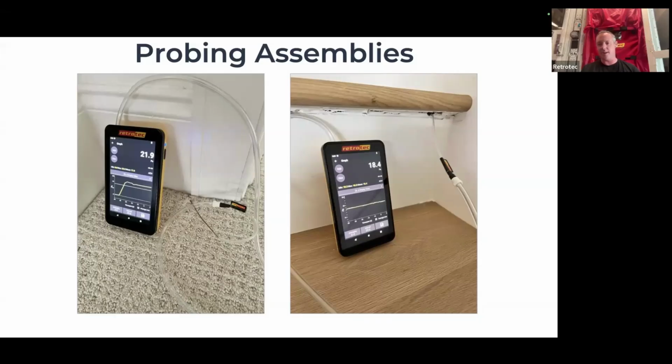Attic knee walls are almost never done right. They really need to be well insulated and have some kind of rigid backing to go all the way down to seal to the ceiling below. A lot of people just seal to the bottom of the wall, but that spot in between floors is where a lot of the problems occur. So you want to make sure you get it all the way down. And here, that's where that problem was occurring, between floors, where those floor joists just opened up into the attic. So it was getting into that staircase and causing that wood to get wet and then dry and then expand and then separate. That's how we fixed that. After we did that, it stopped. We could actually fix it and it would stay fixed.